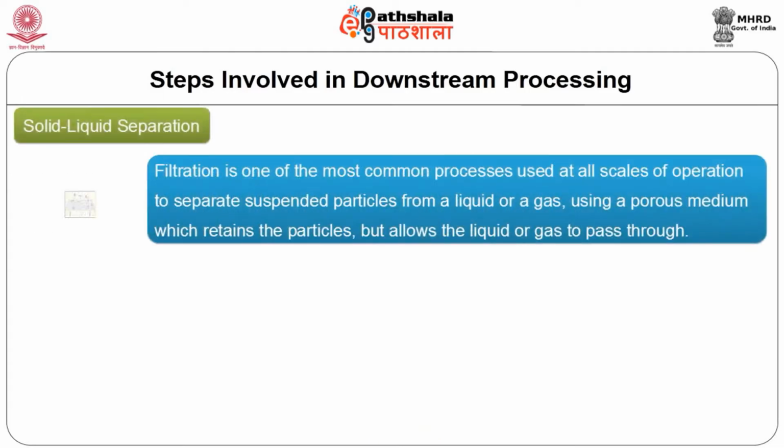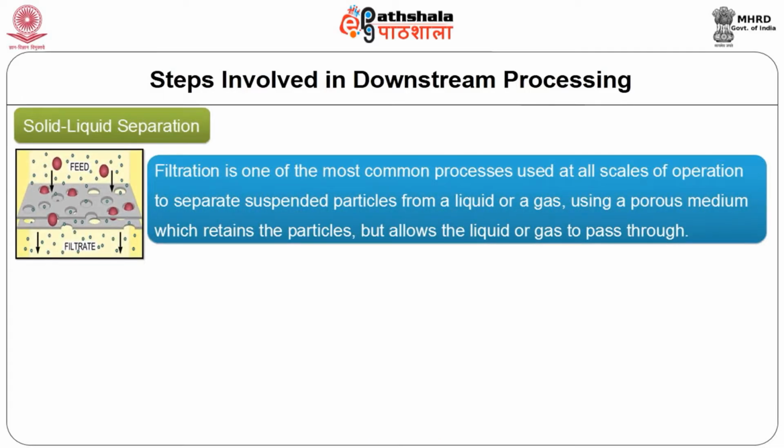Let us discuss the first technique involved in solid liquid separation, that is filtration. Filtration is one of the most common processes used at all scales of operation to separate suspended particles from a liquid or a gas using a porous medium which retains the particles but allows the liquid or gas to pass through.